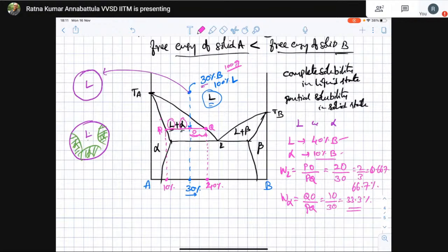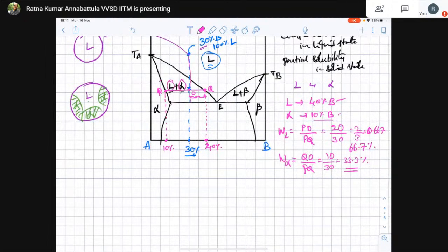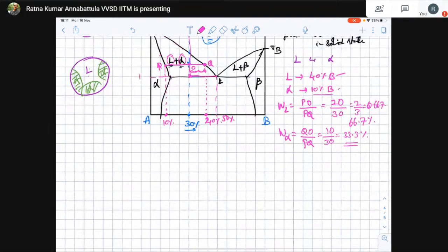Okay, in type 3 alloy, the phase region below the solidus line consists of alpha plus eutectic mixture, or both alpha plus eutectic and beta plus eutectic. Good question. Let us say you are cooling it down. By the time you reach just above this line, if you draw a tie line here, the liquid composition is equal to the eutectic composition. Let us say the eutectic composition is 50% for the sake of argument.